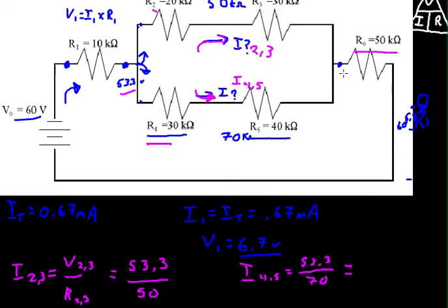So you'll have a voltage drop here and a voltage drop here, and then that's what's remaining for this guy. And then you can multiply the current, which you know is the same, 0.67, by this guy, and then you'll get the voltage drop across from here. So you'll have a voltage drop here, you'll have a voltage drop here. Whatever's remaining will be what was used here. Or you could find this one, whatever's remaining is what's used here.